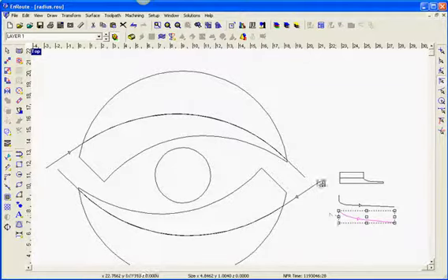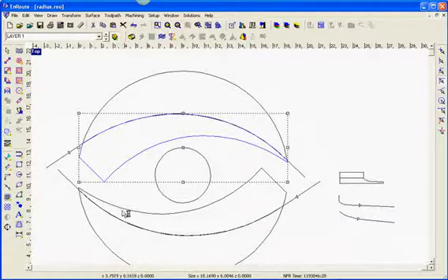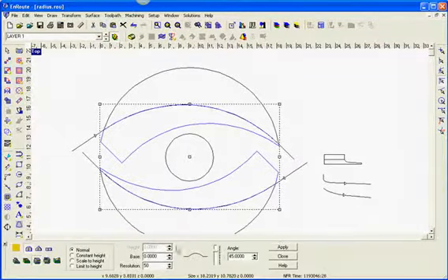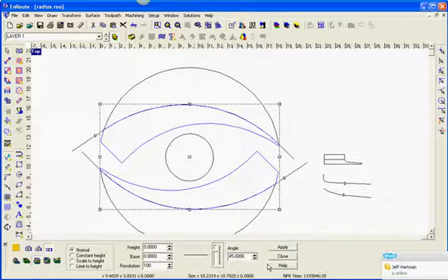And then this is what I'm going to extrude. So basically I'm going to take this corner, put it here. This portion will go out here, and I'm going to sweep this along there. So I'll take these two pieces and I'll do a flat, no thickness relief. I'll do 100 and apply.